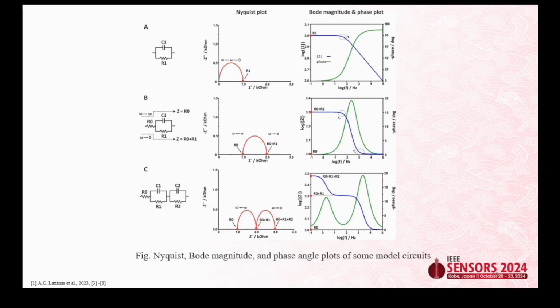So these are some of the basic models that we can use to analyze the system under test, but these are not the only elements. We can always add more and more elements in your equivalent circuit, the more processes that you can explore. That is one of the drawbacks of EIS, that in some cases you add more elements, but you don't understand what the actual processes corresponding to those elements are. So we start with the bare minimum, the basic RC circuit, then we keep on increasing the capacitor or the resistor value based upon which phenomena are actually occurring in your cell.